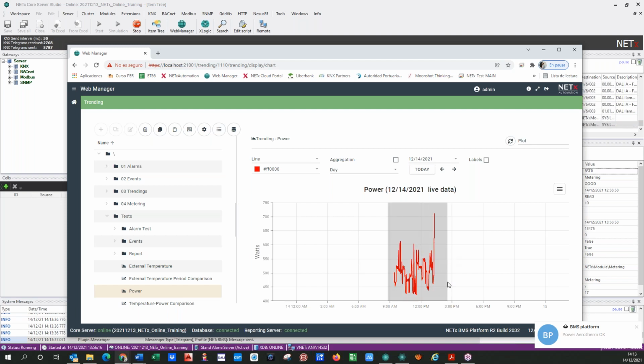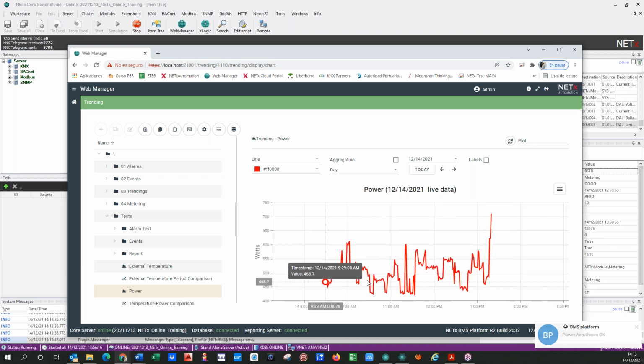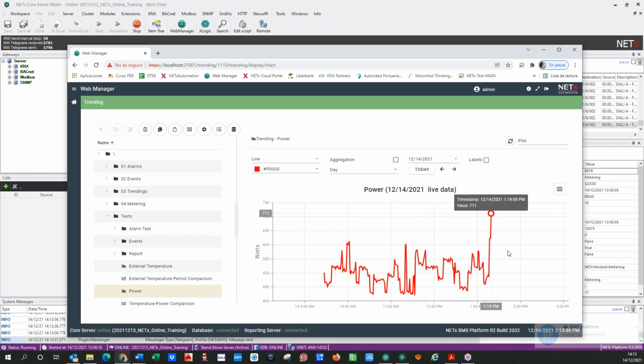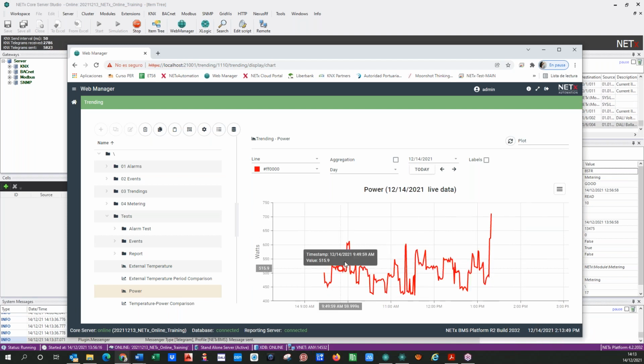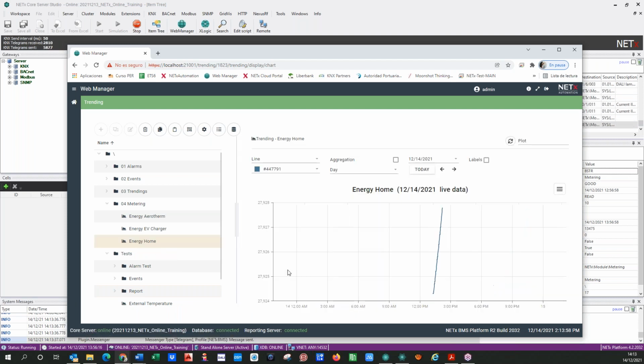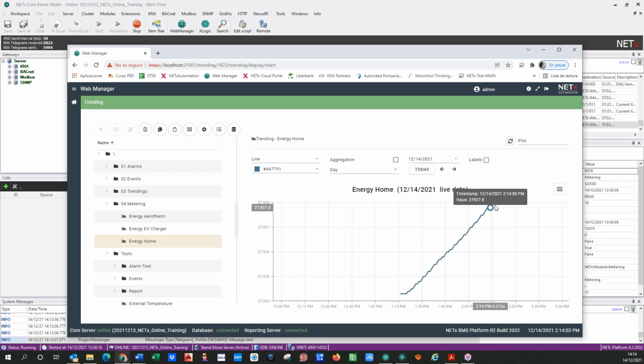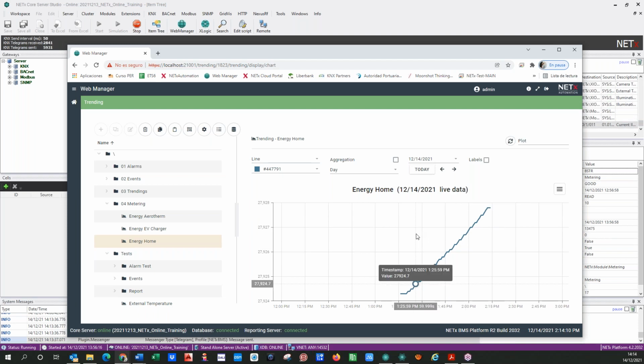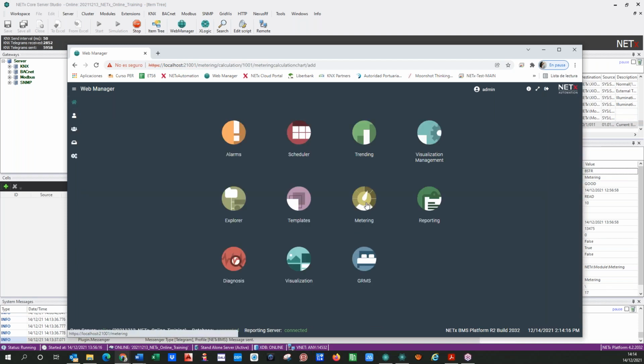So this is not the way. This is just a graphic to see the evolution of the power consumption in your house. That's okay, but it's not the right information to use in your metering module. This one is the right one. It is not useful in this case as a graphic, because it's always going up or standing, but for us it's the data we need. So we need to historize this data in order to see the consumption. Okay, so it's very important.